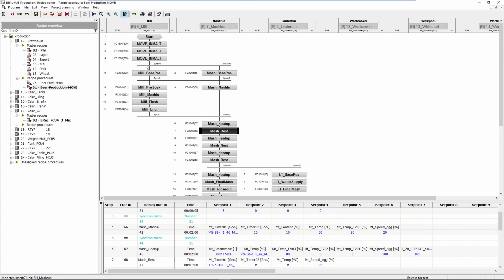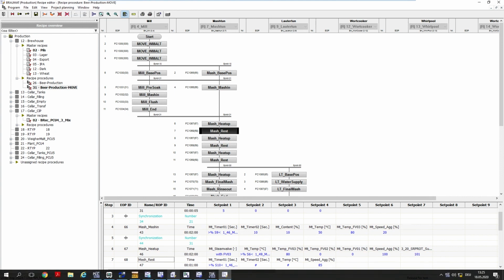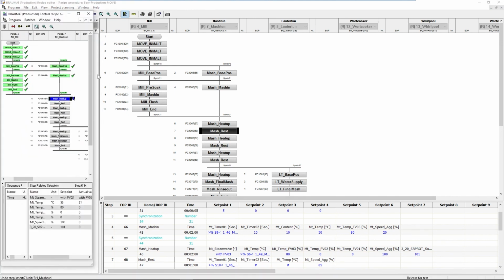These synchronizations serve on the one hand to start a second one from an existing timer position, or to artificially introduce a waiting time at the corresponding synchronization points until these two units are synchronized again. The advantage? These synchronizations do run on the server, not in the AS. This makes the procedure extremely transparent. We can see this here in the online view of a recipe.